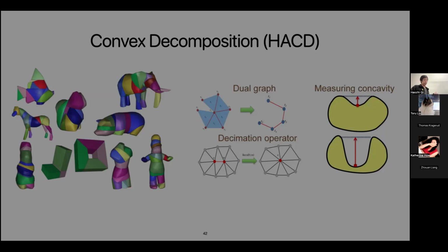So this is one convex decomposition method, which is HACD. You can use an optimization method to run on each kind of vertices, to find what is the possible way that satisfies convexity while being as close as possible to the original non-convex shapes.